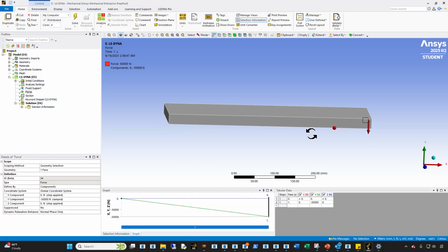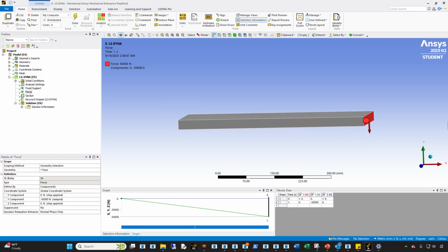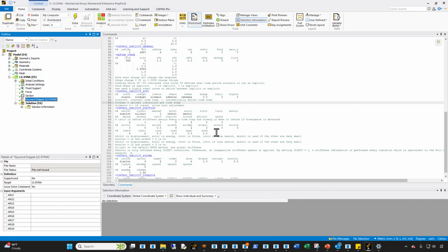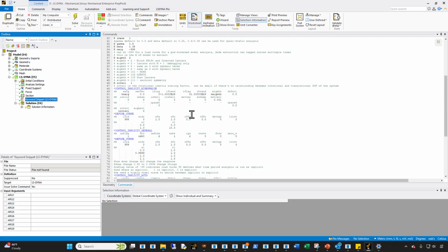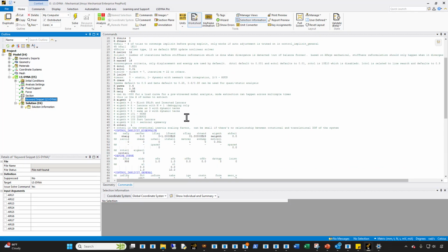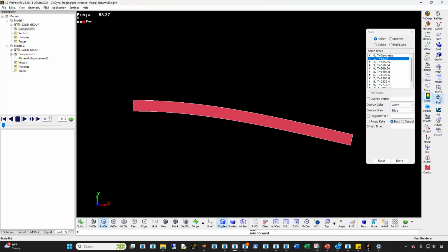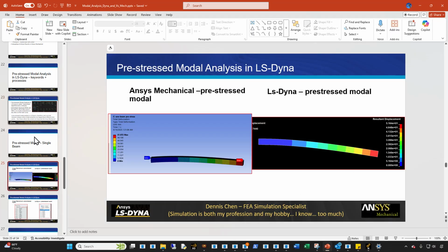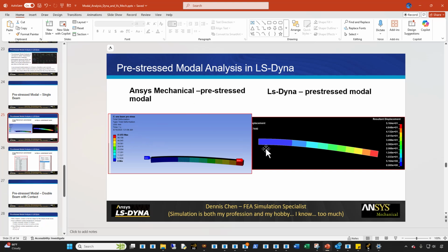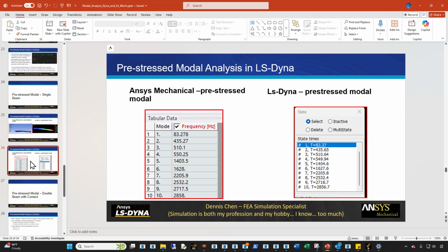This is the nodal force that you're applying to these surfaces, and then you have a deformed shape, and this code template allows you to extract the mode shapes in a deformed shape, just like you can see in all those parabolas right here, right? If you look at the results, you get a pretty clean result. So this is the deformation. They pretty much match between the two codes. This is the natural frequency and the mode shape. They basically match perfectly to each other, right?